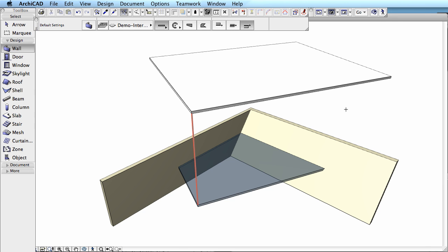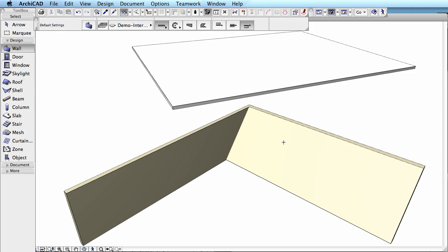Let's see how we can use editing planes in 3D views. Here, our task is to reproduce the transparent blue slab at a given height surrounded by these walls. Please note that one of the walls is slanted. The new blue slab must be in projection to the existing white slab. Currently, we have only 2 intersecting walls and the upper slab.